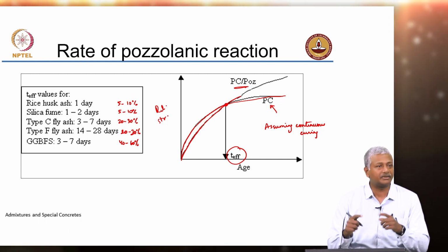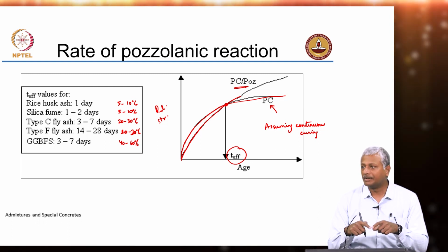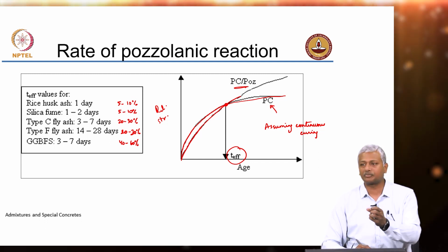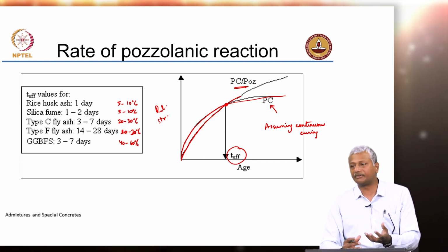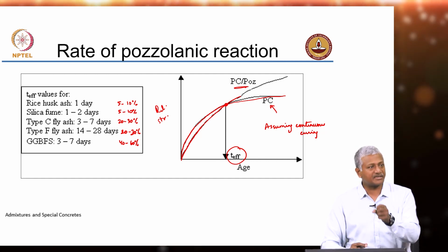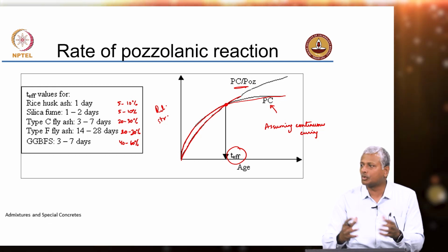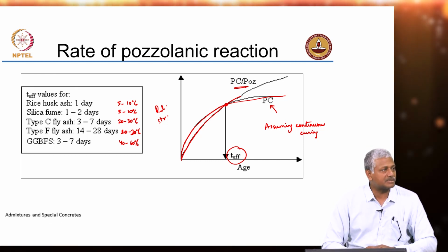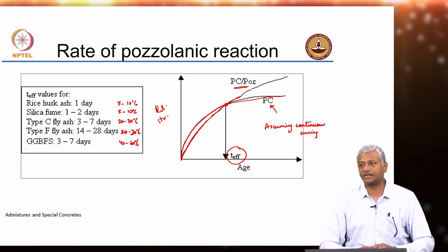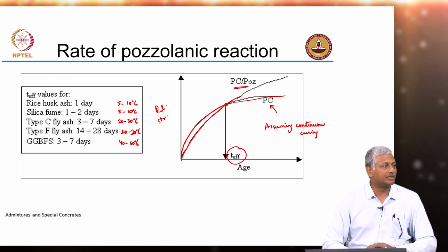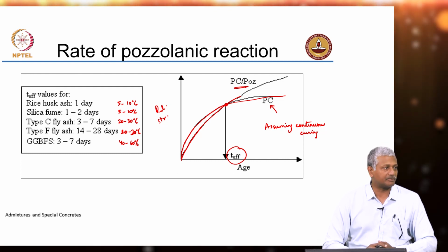We saw in the earlier discussion of cement chemistry that you are filling up the available space with hydration products, and these hydration products were a lot more voluminous as compared to the initial cement grains. So, once the space is not available, you do not have space for these products to grow. So, you are going to be constricting or restraining the extent of reaction that can further proceed. All reactions are usually limited because of the lack of space.